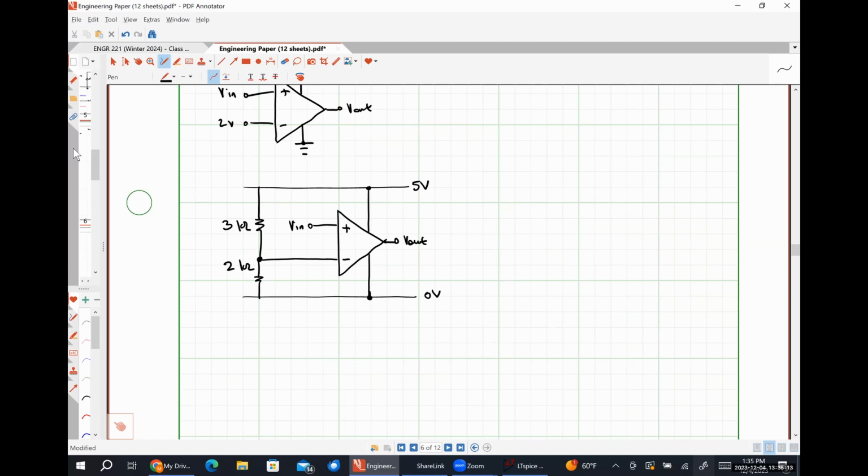What are you trying to solve for? Yeah, so I1 is equal to 0.1 IY. And then IY is I2 minus I3. And then you'll do a KVL equation around this one, KVL equation around that one. And that's not your Norton current, that is your test current. But that's just gonna be negative I3.